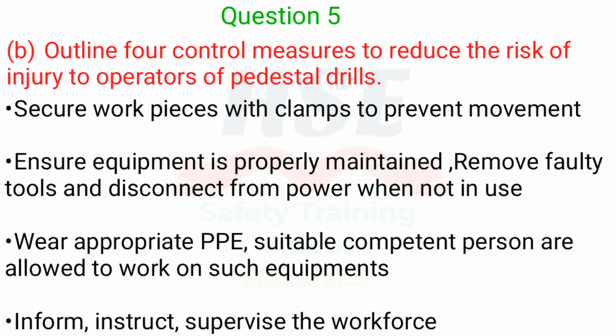B. Outline 4 control measures to reduce the risk of injury to operators of pedestal drills. Secure workpieces with clamps to prevent movement. Ensure equipment is properly maintained, remove faulty tools and disconnect from power when not in use. Wear appropriate PPE. Only suitable competent persons are allowed to work on such equipment. Inform, instruct, supervise the workforce.